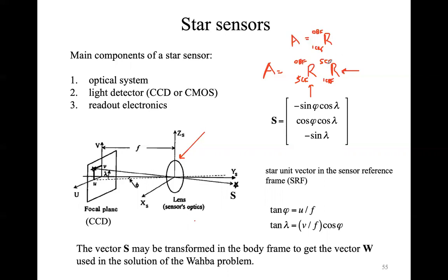So you need to multiply it by this known matrix in order to have the attitude matrix. For our purposes, we are assuming that this is known and almost constant, so we are excluding important rotations between the star tracker reference frame and the body frame.